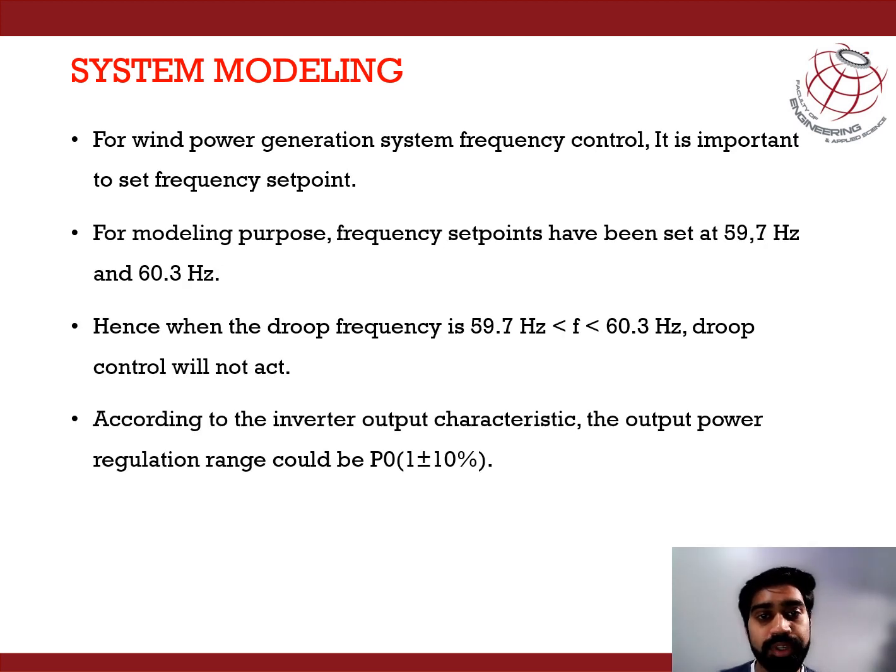So in the MATLAB simulation, we have set the frequency set points at 1% deviation. So frequency can vary from 59.7 Hertz to 60.3 Hertz. Apart from that, active power also can vary 10% from its rated output. So in the upcoming slide, I'll present the simulation.